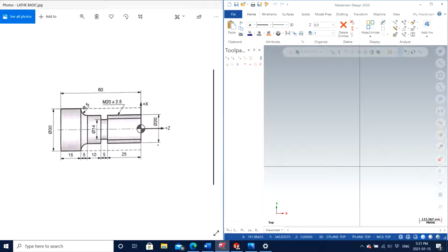So if we talk about Mastercam software, it allows you to either make a 2D sketch of the model that you want to machine, or you want to visualize how it looks when it is getting machined, or you can simply bring it in by using the merge function that Mastercam allows us to access and merge a different software part, which may be a step file, it can be IGS file, or there are different formats that Mastercam supports.